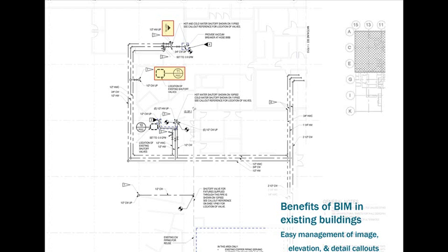Something else we did was elevations for patch and repair. Because we modeled the whole building, with a bunch of pipes starting from wherever the water was coming from in the main all the way out to each fixture, and we had a BIM model of the building, we could cut sections or elevations for these different walls. And we could put those onto sheets.